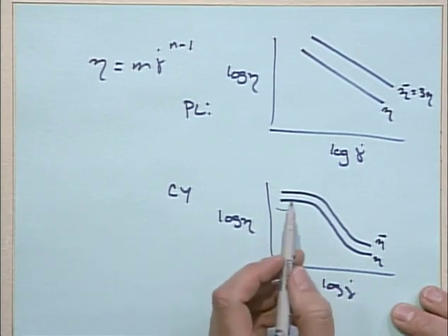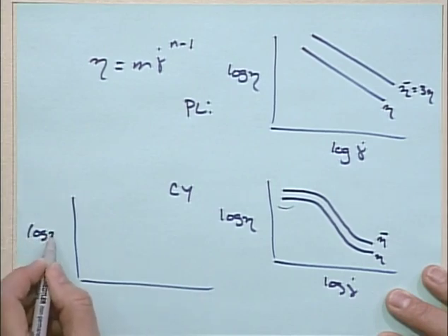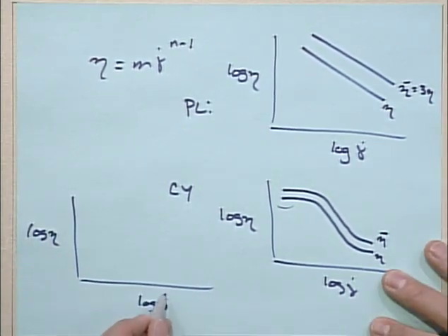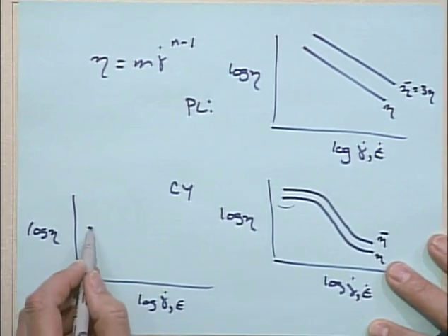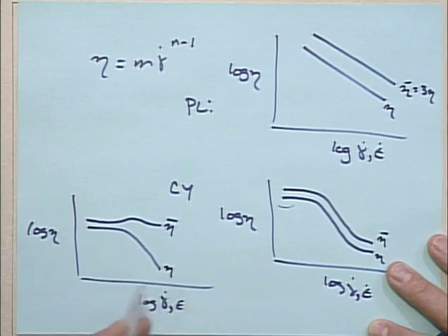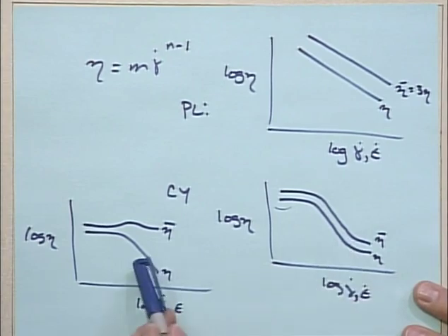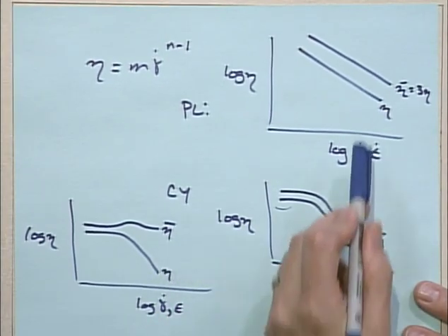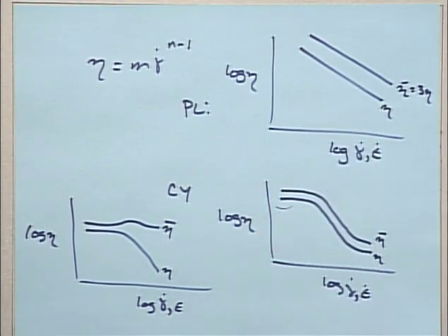The data we saw showed that even on polystyrene, either shear rate or elongation rate, what we saw is that when it's a shear thinning fluid, very often it can be a little bit like that, a slightly shear thickening fluid. So this isn't very accurate here. So the power law, the generalized Newtonian models have this mirroring effect where one just mirrors the other. And that's not accurate.